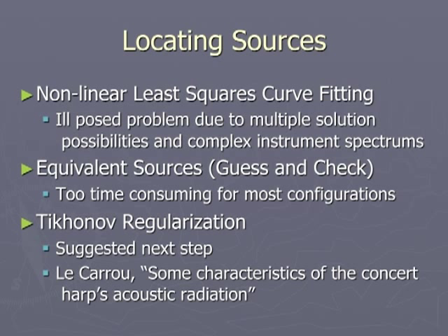The next step will be to automate this process of determining the equivalent sources. In the paper by Le Caroux, a method is outlined for using Tikhonov regularization to compute the output of the inverse of the transfer function from sound source to microphone input. We recommend the implementation of the Tikhonov regularization as a future project for engineering physics students.